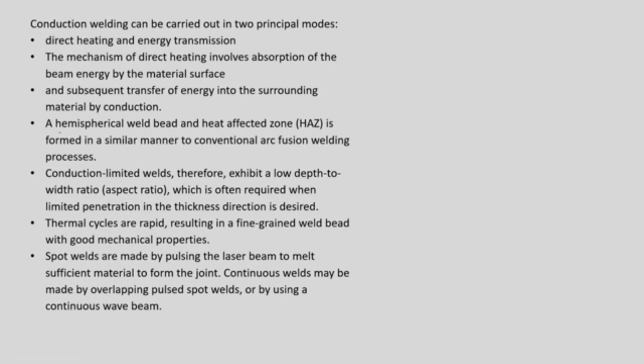Now in particular, as I mentioned, we are getting a hemispherical weld bead and there is a HAZ, heat affected zone, as well, which is very similar to the conventional arc fusion welding process. So as I mentioned, we are getting a low depth to width ratio, which is a limitation when penetration in the thickness direction is desired. That is a limitation of the conduction mode of laser welding.